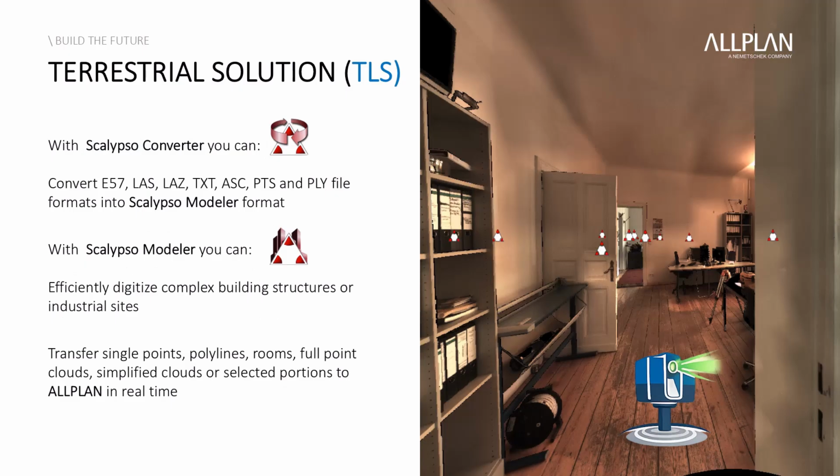Now let's look at terrestrial solutions. If the point cloud comes from a terrestrial laser scanning type of instrument, which is a stationary ground-based solution, Allplan specifically provides the Scan Modeler tool. In the workflow designed for using this tool, what do I need to do? I will now use the powerful Scan Converter tool to efficiently convert the most common point cloud file formats into a specialized format that can be read directly by Scan Modeler.